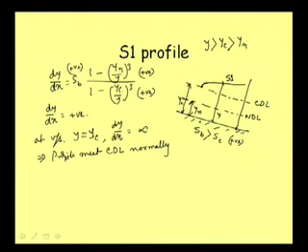Then there must be some disturbance, maybe some obstruction like a dam or anything, and then the flow is rising, crossing this part. Again, there will be some control section at the downstream, and before the S1 profile starts, there must be some flow profile here which will lead the flow to move from normal depth to the critical depth line.